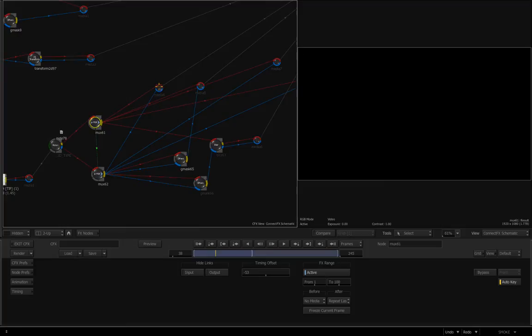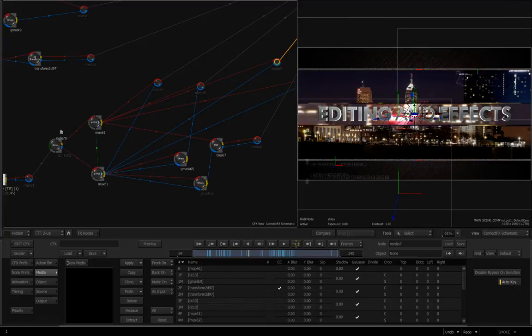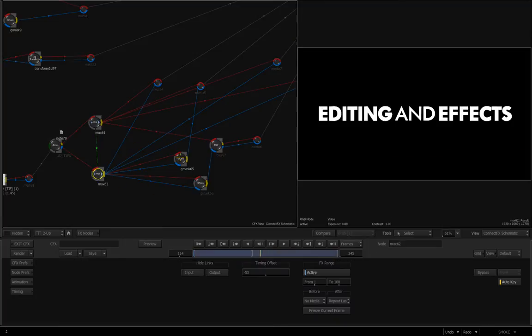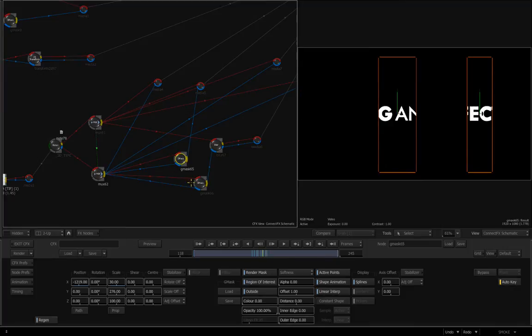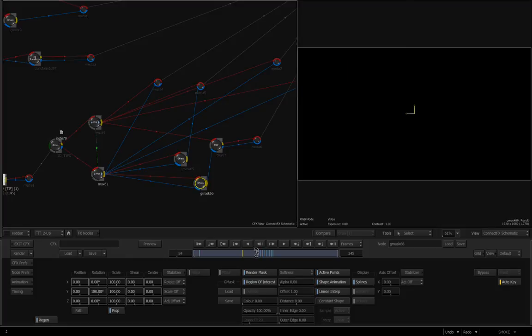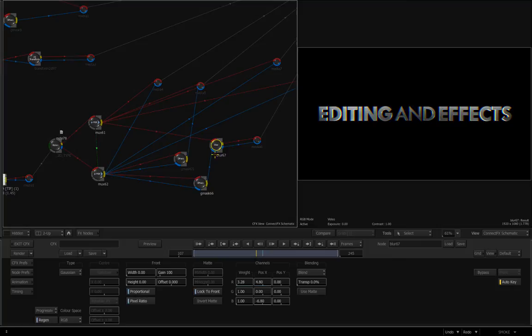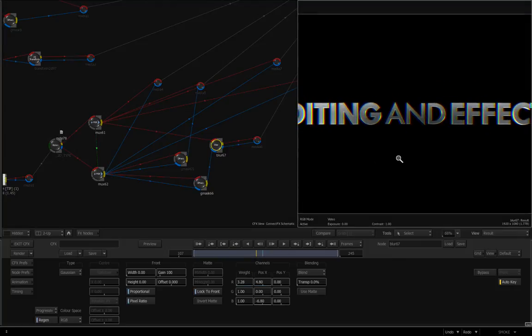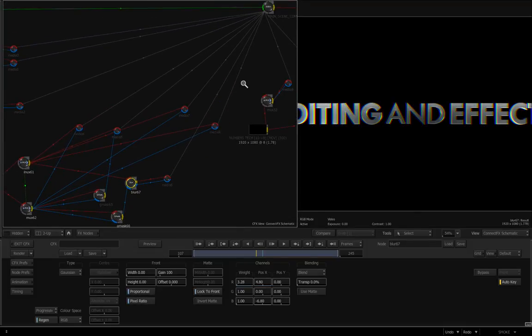You can see that this then feeds into several action media layers, because I start doing some stylization on this type, adding glows and light effects to it. Out of this mux node, I run it through a Gmask node that does several little wipes to reveal different parts of the text. Another Gmask node does the same thing, but slightly differently. So I have all that running into a blur node, giving it a little RGB offsets.